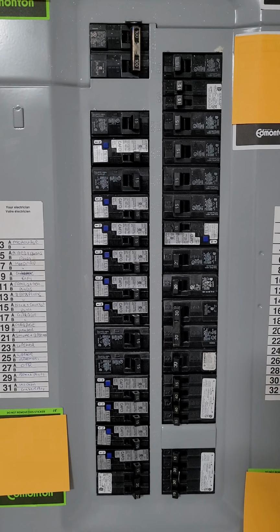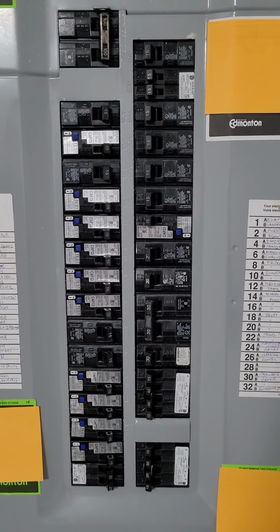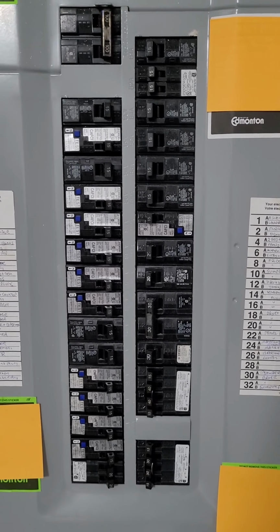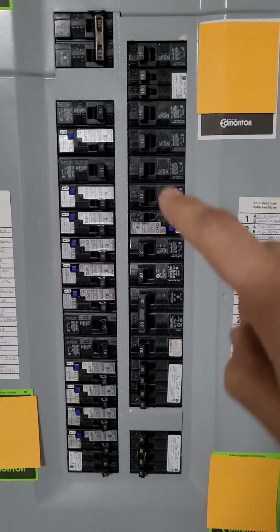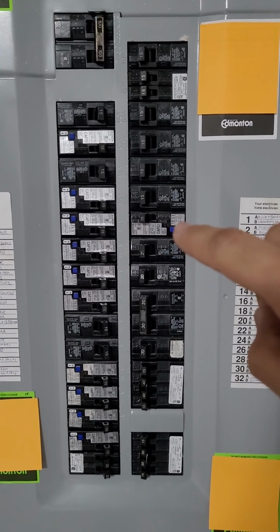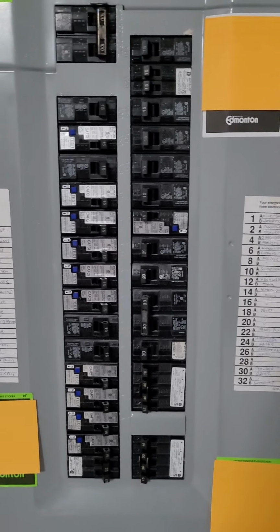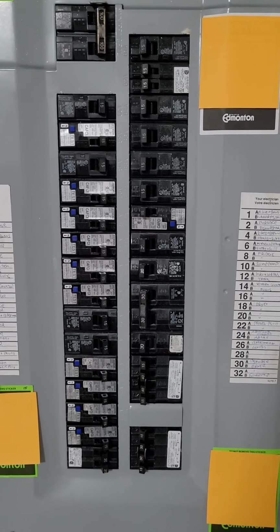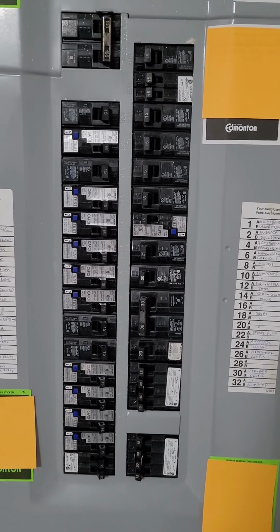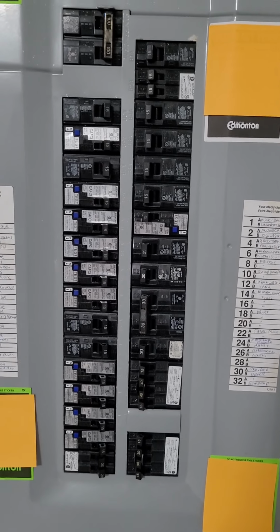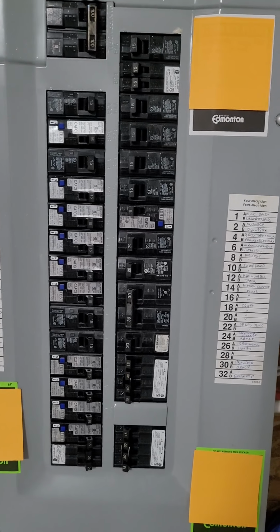on the breakers. Now the third type of breaker is GFCI breaker, which is ground fault circuit interrupter breaker. We don't have it here, but it's usually the same kind as AFCI but with a yellow button. So what it does is it protects outlets from ground fault. So for example, if there is any loose neutral or loose wiring, it will trip it off, or if there's any moisture that can cause a shock, then it will trip it off.